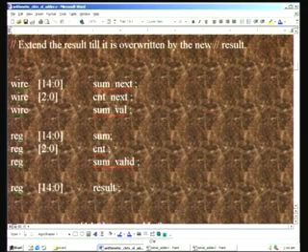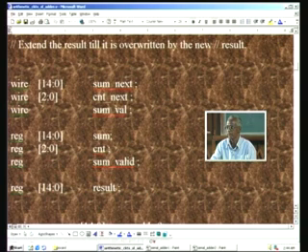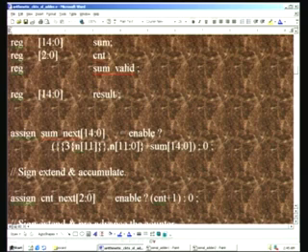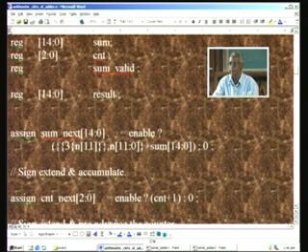And so is the case with the counter, that is also in a positive edge clock, and this is only 3 bits in width. This is also a register sum valid, which indicates when the sum is valid, and this is going to be valid only for 1 clock duration, and result is same as sum, except that it is going to be valid for 9 clock cycles, so that when we do the computation of the next set of numbers consisting of another 8 inputs, then we will be updating this.